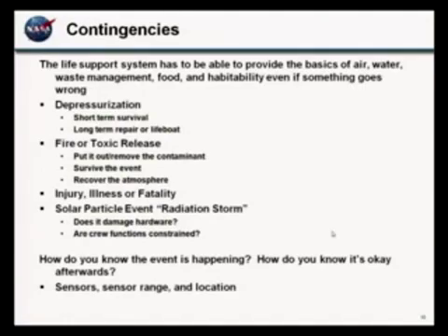After that, you need to decide what's your long-term plan. Can your vehicle be repaired? Can you get to the outside? Well, we'll assume that this is a hole that is small enough that you can identify it and see it, and it hasn't just completely split the vehicle in two. Like I said, there are some things that are just maybe not recoverable from. But if you decide that your mission is so long you'd better be able to fix a leak and recover full capacity of your vehicle, you have just basically written yourself a requirement for either sophisticated robotics or significant EVA capability to get out there and access any point where something might have gone wrong.